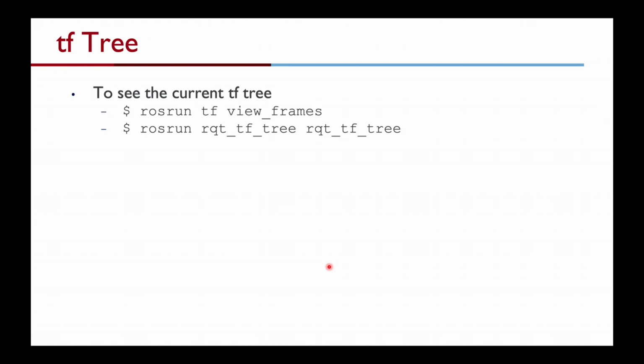And you will see this example, the command which allows you to view the TF tree is rosrun. The package name is tf, and the command is called view_frames. A frame is just ROS-speak for a transformation; each of these transformations getting broadcasted is called a frame, so we can view these frames and the rate at which they are getting published. You could also use the rqt tool to visualize the TF tree. That's pretty straightforward as well.